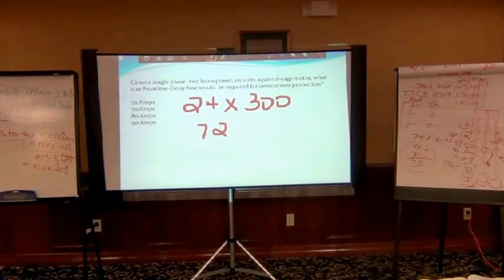Is this one of those questions you get with that little...? I would. I mean, in this case, at 72 amps, you're going to be close enough that 70 is pretty obvious that it's probably a breaker. But it's good practice to keep in mind that you'd then go back to page 91, double check your standard size breakers, pick the next lower size.